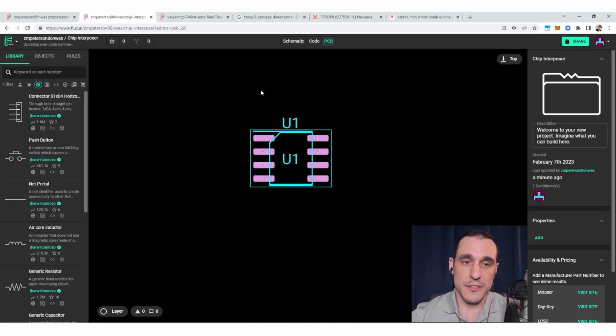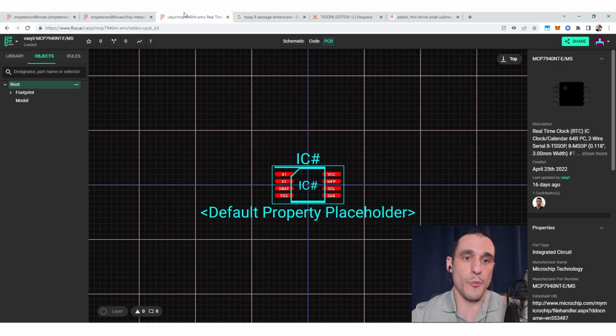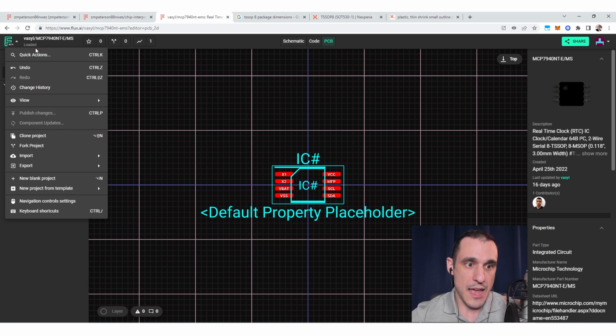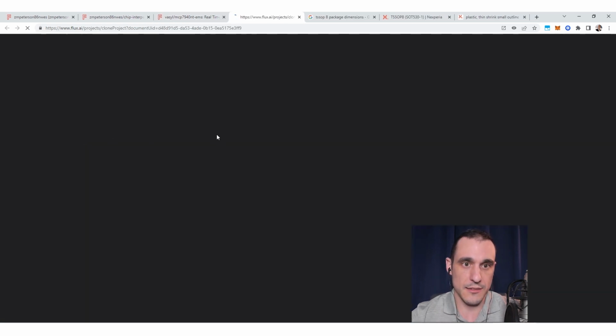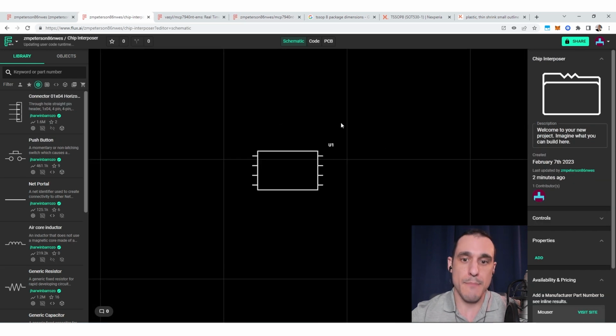So to get started with this, first, of course, I want to define my translation between this footprint and this footprint. And so to do that, I need to take what is my existing component and then define net connections to whatever my new component is going to be. So the first thing that we want to do is actually take this component and clone this. The reason I'm cloning it is because I want to have a copy of this component that I own, and because I own it, I can now modify the pinout so that it matches the actual component that I'm going to use to then match up to this existing footprint in my board.